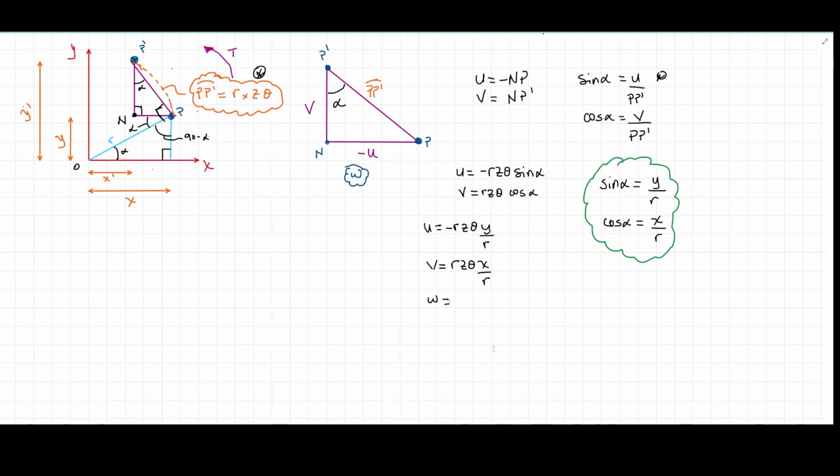That function has a name that people have adopted during the whole development of the Saint-Venant process. And that's going to depend on x, y, and the twist angle. So warping is going to be represented by a function of x, y, and theta.